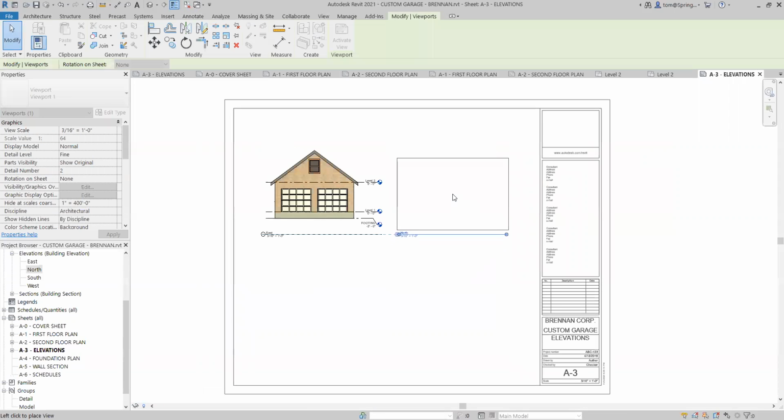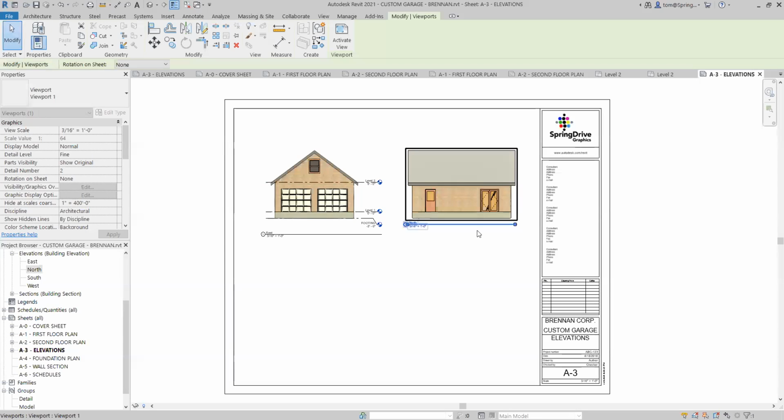Now notice what I get here. Watch what happens when I pull this over. All right, notice that right there? See what that's doing? It's actually giving me the roof line. It's actually aligning the roof line, okay? And I could try to pick up these right here to put up the roof line. It's picking up the roof line quite nicely. So I can move the title later, but I definitely want the roof line to be aligned. So I'll click there, drop it, and boom, those are now perfectly aligned, okay?